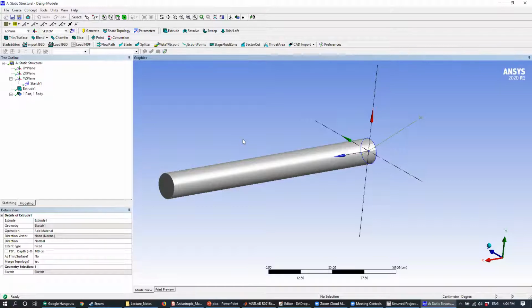So we saw a little bit of this already in Ansys Activity 3, because if you remember, we did the Ansys analysis of a signpost. In order to apply our wind force on the left-hand side of the signpost, we had that phantom surface there that bonded to the structure so that we could apply that wind force on that small thin part. Okay? So all of those things would be great for this.